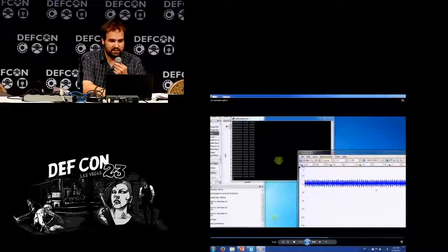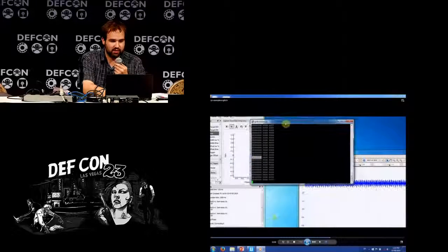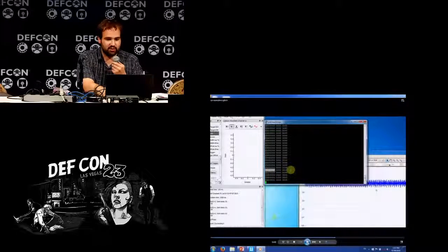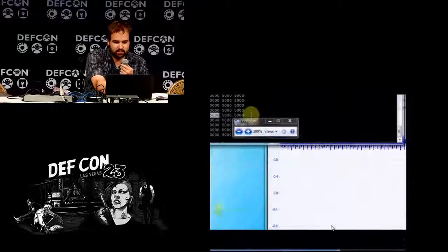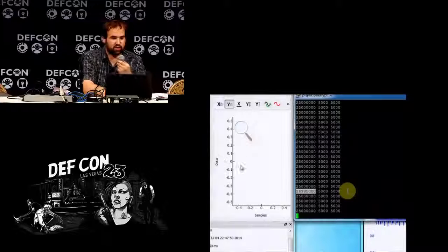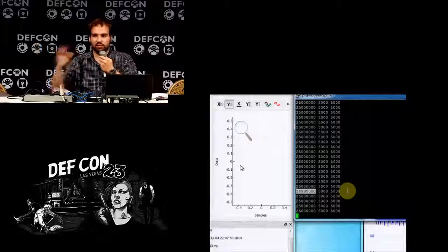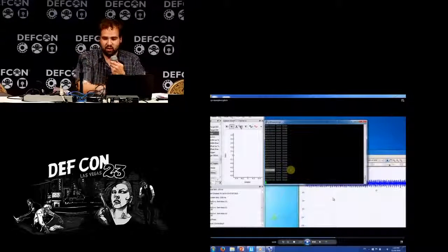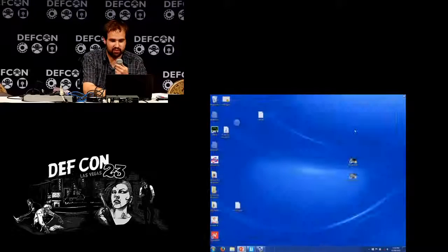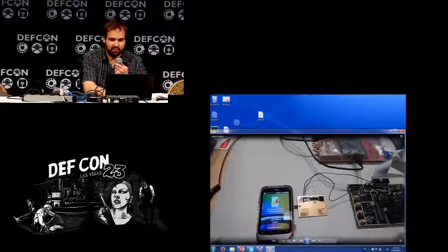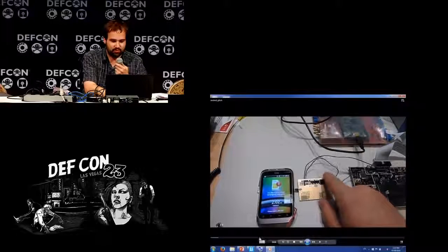And what you might see, I think I run it again here, is that the count value, when I hit trigger, becomes incorrect. I don't know if it's too visible, but you can see this count value here. It skipped out of that loop at one point. So the glitch didn't crash anything else. It's still pinging the board, everything like that. It just caused some incorrect code path to be executed. So that's the interesting thing you can do with glitching: you're causing entire incorrect code paths to occur, and then you can use that for bypassing various security measures.